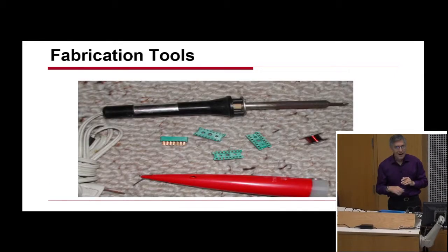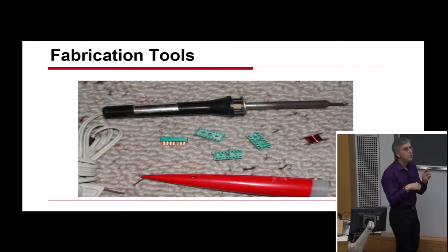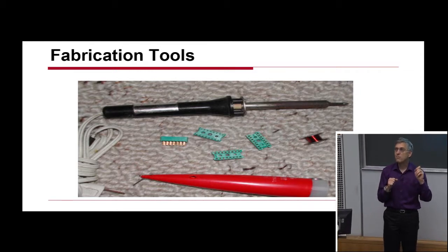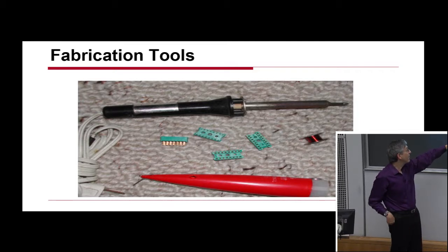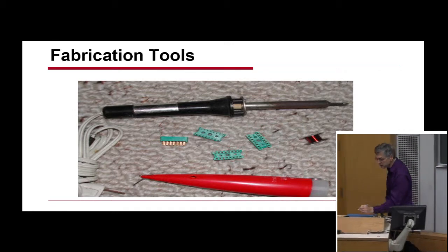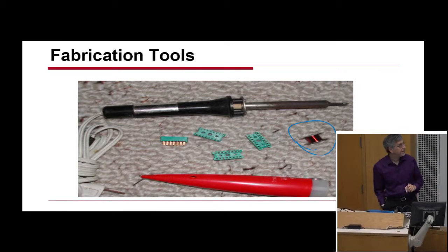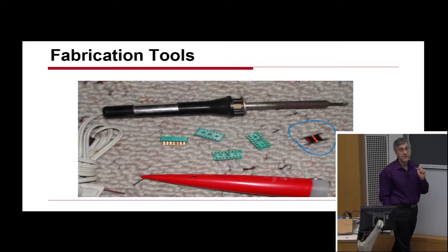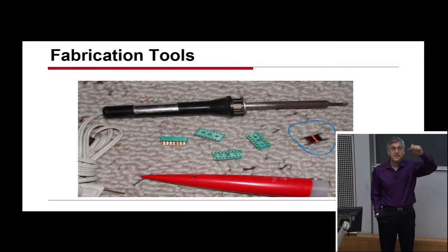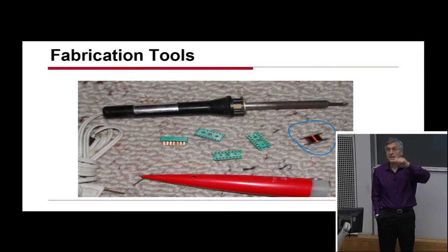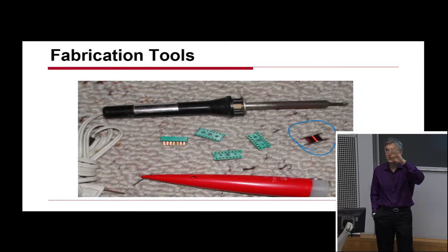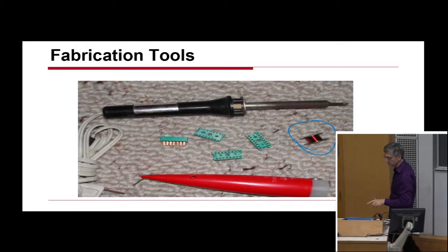And then I was actually too poor to even do wire wrapping, which was the right way of putting together things at the time. There was this cheap alternative called a wiring pencil, which had that spool. This thing over here is a spool of extremely fine wire. It had insulation on it that melted at solder temperatures. So you basically wrapped it around the pins of sockets, and then you soldered it, and the wires connected where you soldered it, and you could wire things up. So that's the way I wired things up.